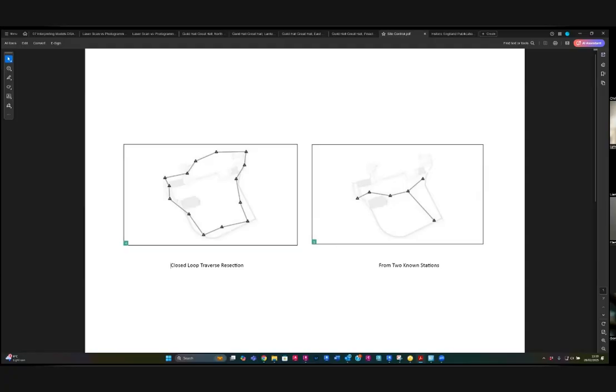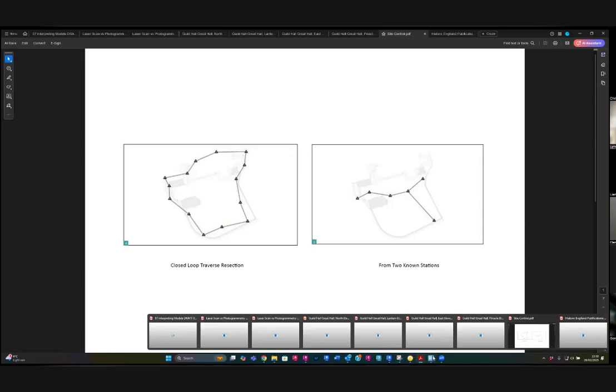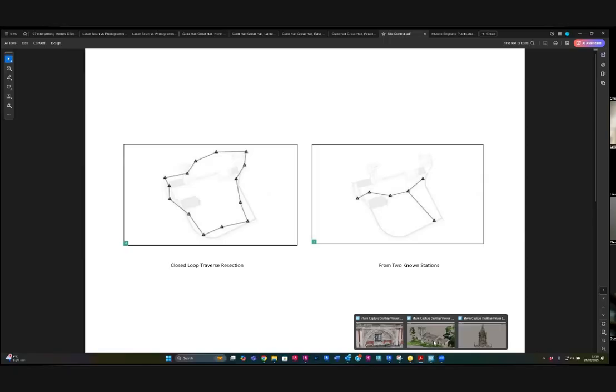And often we get challenged because people don't appreciate that they mix resolution with accuracy, and sometimes there's existing data, sometimes data's merged. So you sometimes want to interrogate your point cloud data to find out which of the sensors or which of the flights or which of the surveys collected that data point.